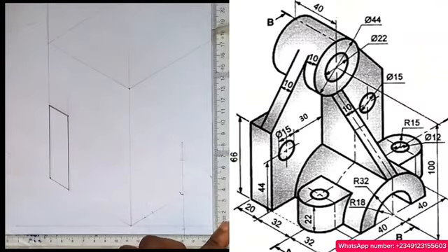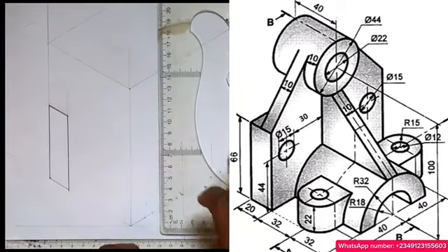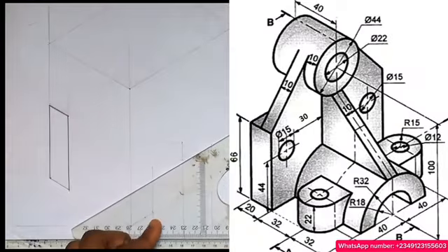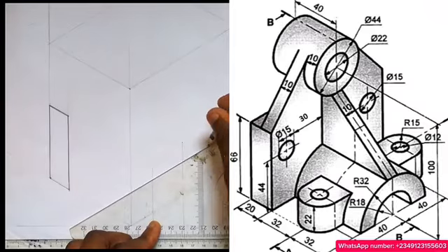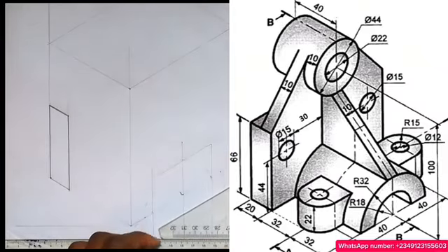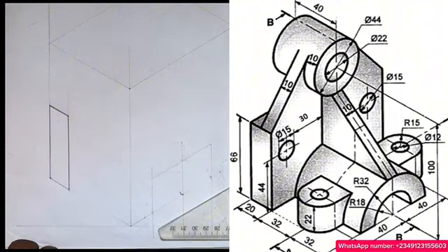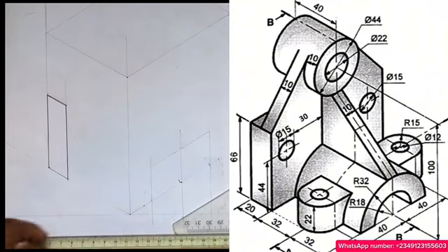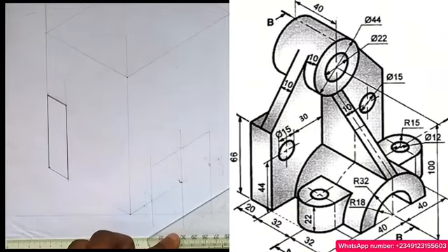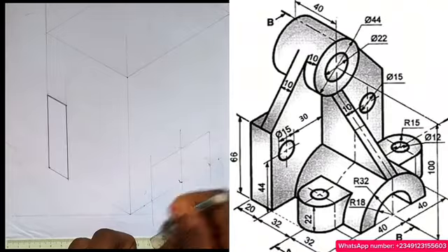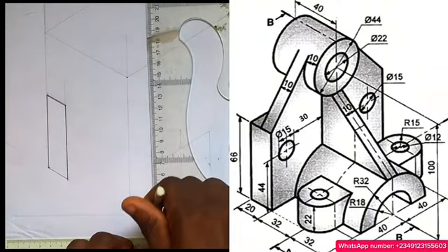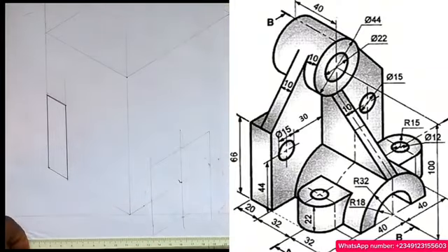So I'll take this point here where it meets here, take it down with a faint line. Take this point here too, down with a faint line. As you can see, now use this one here to close them up. I'll close this point here to this, right? I'm using the principle of ordinate method of construction of circle to produce that, right? So I'll link up this to this way. I'll take this down this way, right? So that I will take this one here down to touch this point here, right? So this is what I have here.